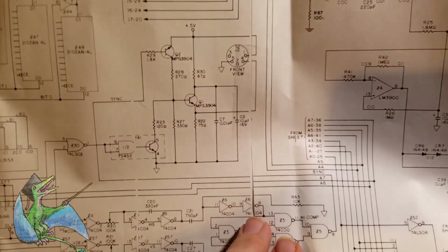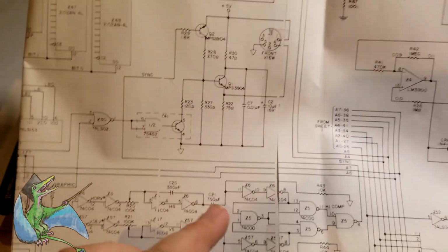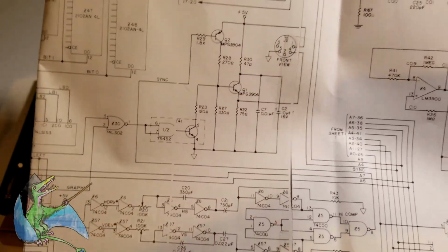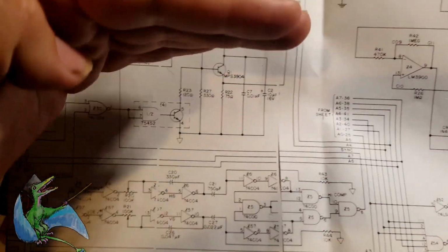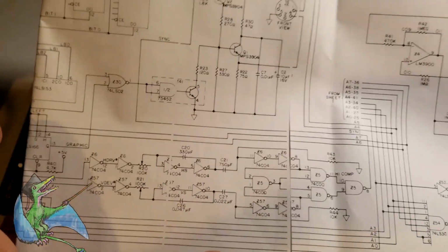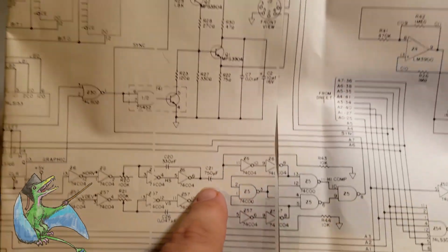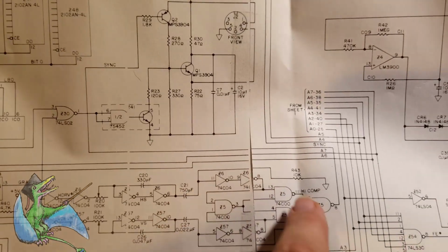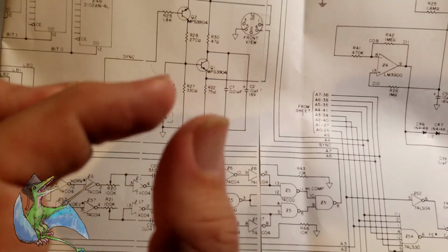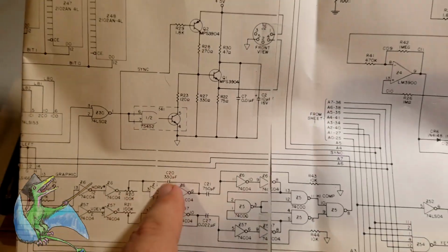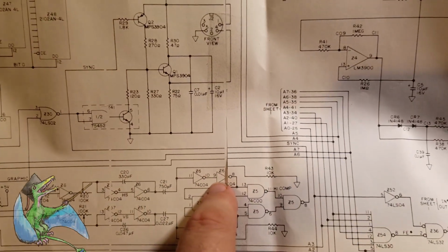Now, the last step here is essentially the transition that it's getting from the H-drive pulse. The H-drive is actually high for almost 2/3 of a line, and that's way too wide to be an actual H-sync pulse. So this section, which consists of another capacitor and a resistor to ground, determines how wide a sync pulse is created by the transition that's delayed here. So that's what the last two gates are for.